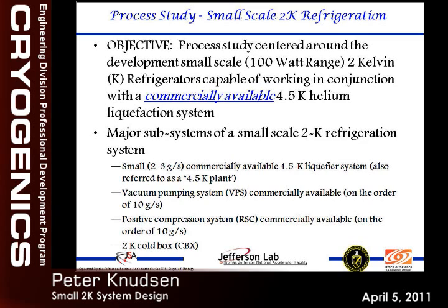The objective of this process study is centered around the development of a nominally 100 watt, 200 watt range, 2 Kelvin refrigerator capable of working in conjunction with a commercially available 4.5K liquefaction system. And the major subsystems for this small 2K subsystem involve, as I mentioned, about a 2 to 3 gram a second 4K liquefier.